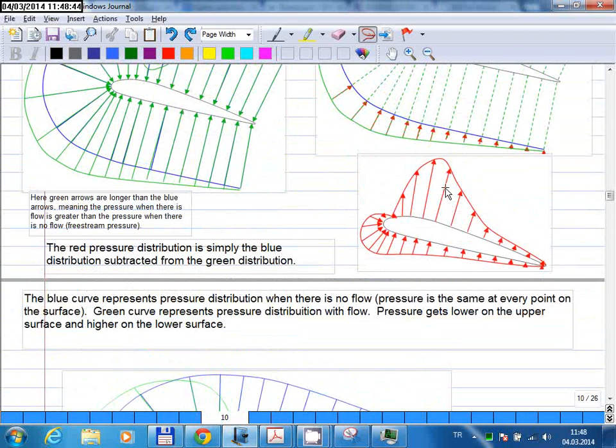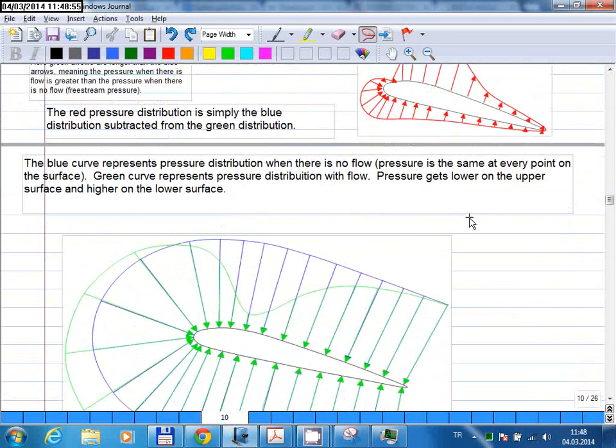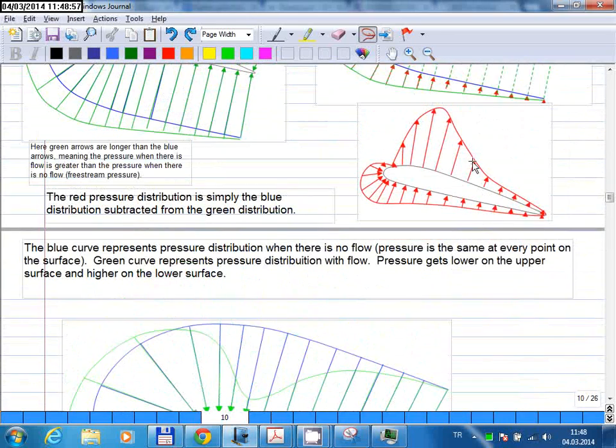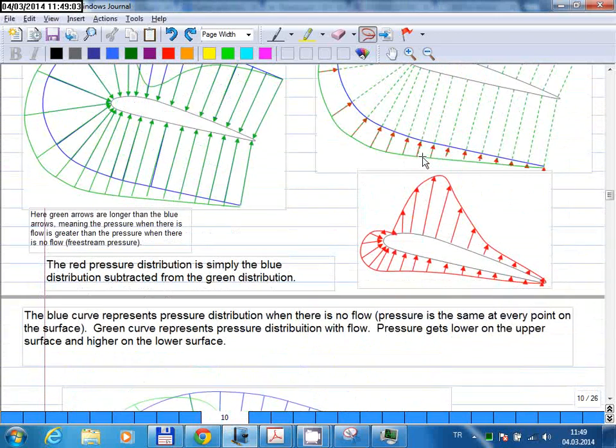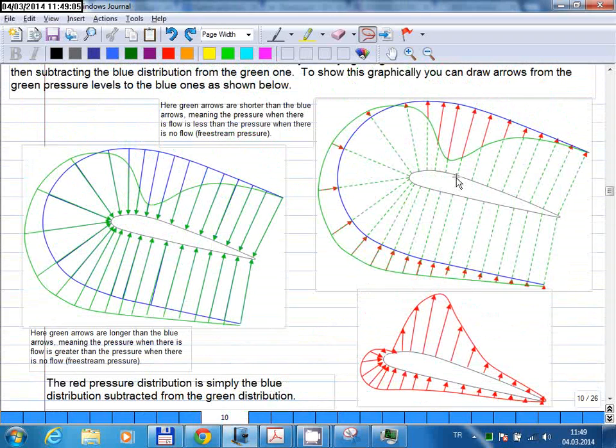Okay, so whenever you have an airfoil and an airflow around your airfoil, there will be a non-symmetric pressure distribution. This shows a pretty typical pressure distribution for a typical airfoil. You see that the pressure drop is maximum here, which is where the flow acceleration is maximum.